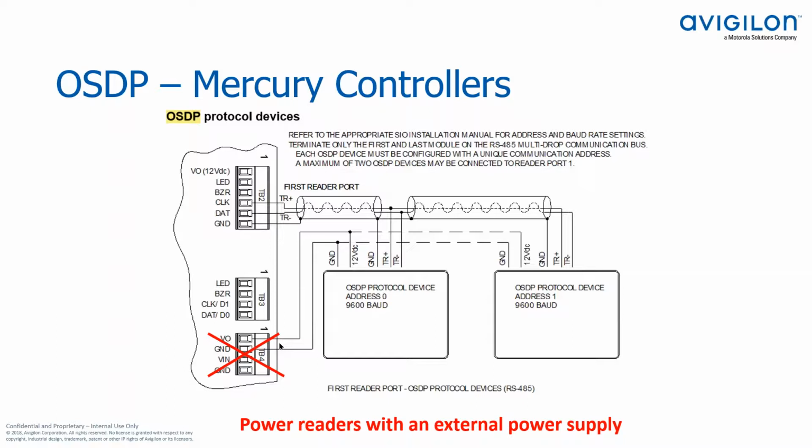Okay, so for multiple readers, please provide an external power supply. I know I'm beating the horse to death in here. Just want to make sure that everybody understands that it's a problem there. Okay, so make sure that you provide an external power supply.